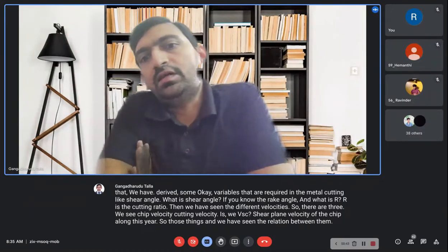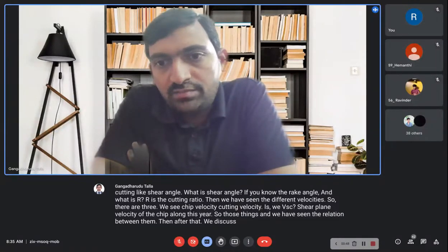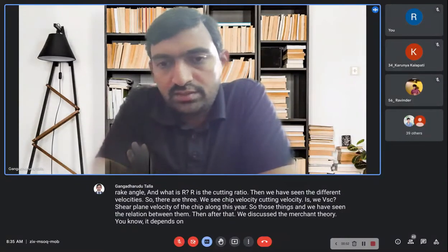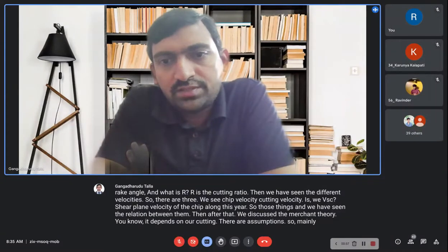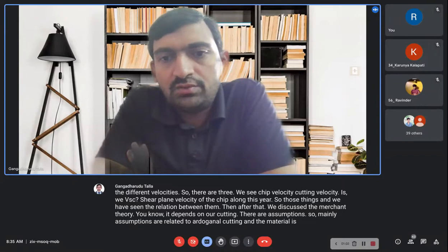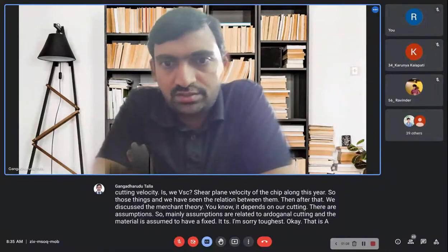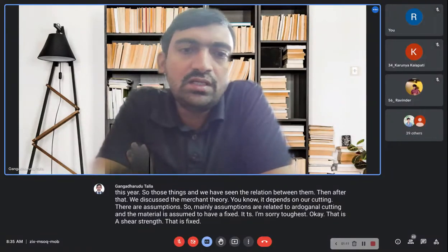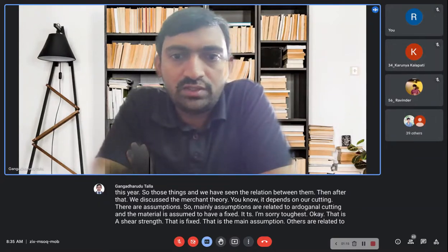Okay. Then after that, we discussed the Merchant theory. It depends on orthogonal cutting. There are assumptions. So mainly assumptions are related to orthogonal cutting, and the material is assumed to have a fixed tau s. Okay, that is shear strength that is fixed. That is the main assumption. Others are related to orthogonal cutting only.